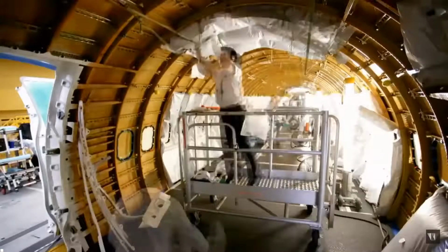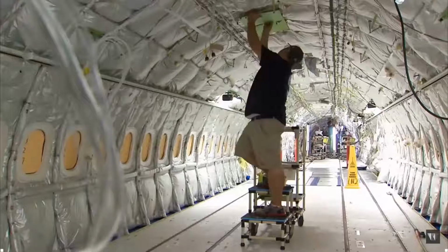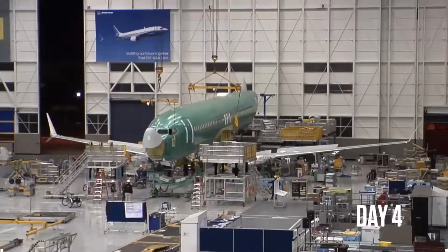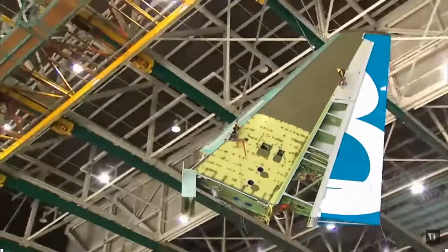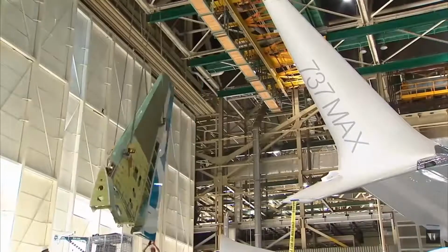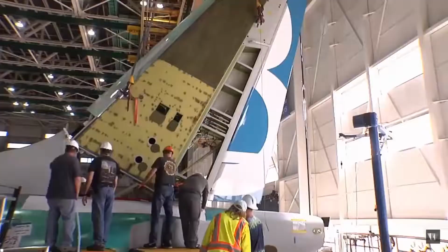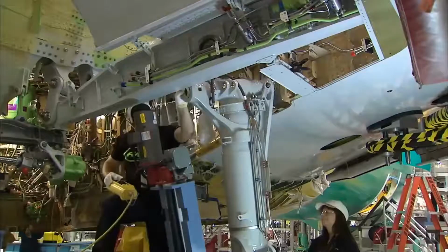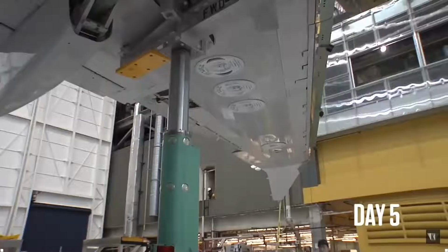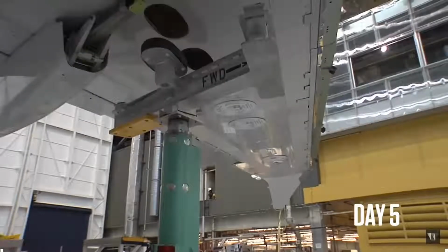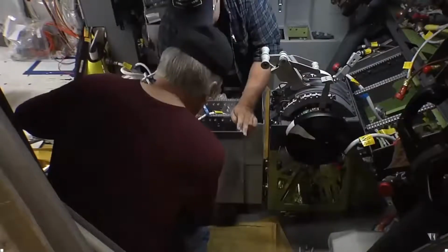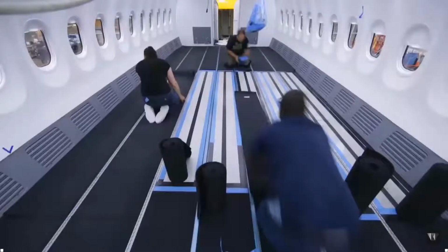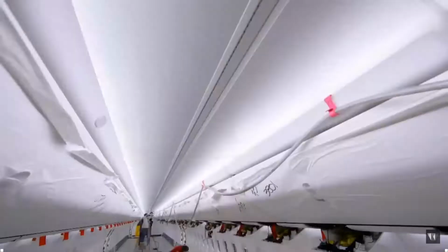It's like building a house. First, engineers install the plumbing and electrics and the insulation. But it's also project management. On the 4th day, the tube becomes a plane. The wings go on, along with the vertical fin or tail. Workers align them with laser guidance. This is when they fit the landing gear too. Day 5 is for the horizontal stabilizer install and the start of functional tests. Engineers are putting wiring in now for flight control and finishing the internal floorboards. They start building the interiors up, the galleys and the bathrooms.